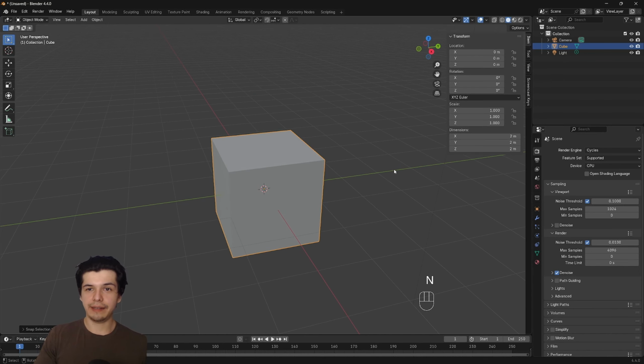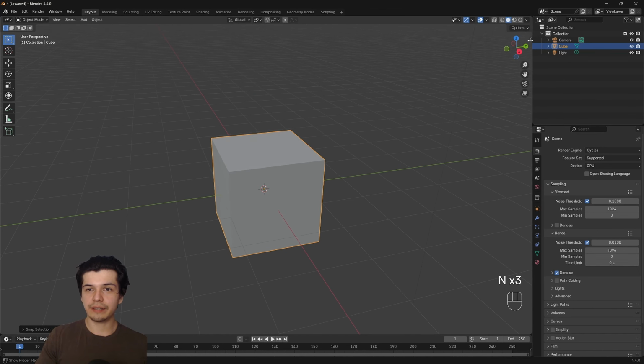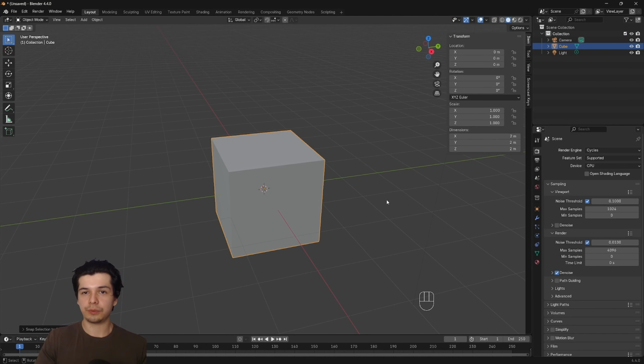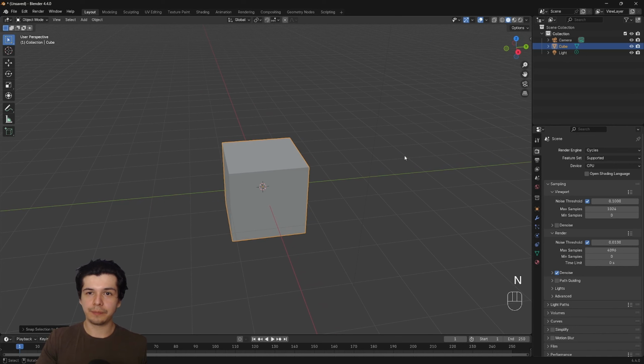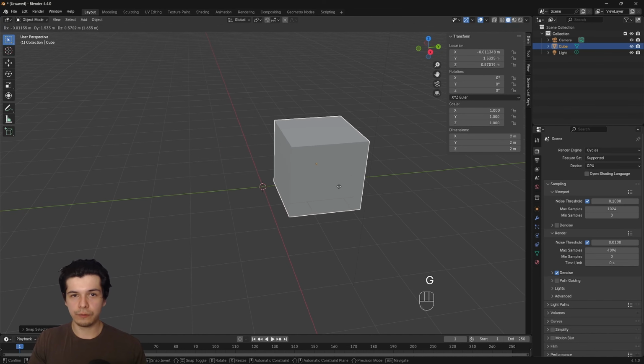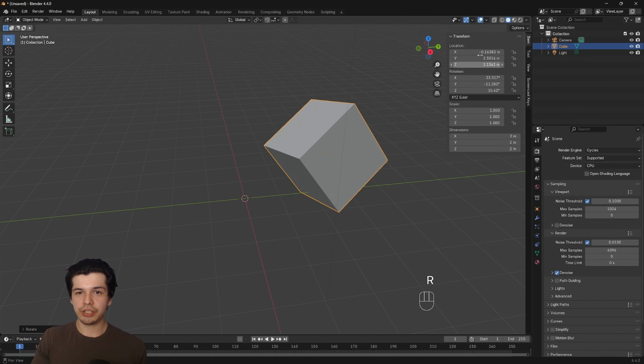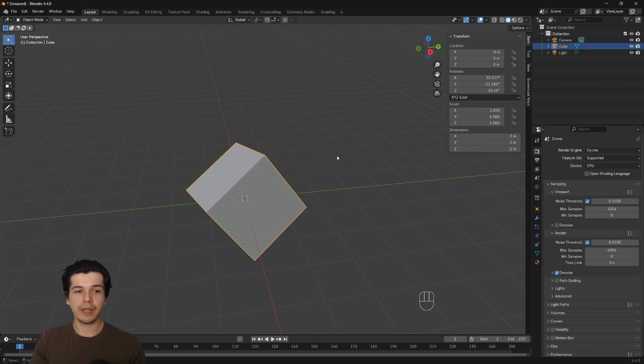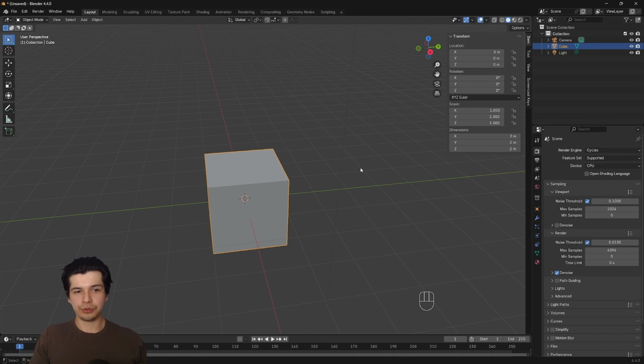Now, if I'm gonna press N, or I'm gonna go right here, there is this arrow on the side. It's very small, but you can see here in the corner, it allows me these extra options. Or in the viewport, if I'm gonna press N, it hides and opens. This is important for us because if we are in object mode and we have moved or rotated the object, you can see it changes the values here. This also allows me to go back from here. I'm gonna left click this one and drag it right away. You have to do it quickly. I'll drag it down. I get all these numbers. I'm gonna press 0 and it brings me back. The same with rotation. 0, I'm back. So this is good to know. If you use object mode for these things, you can get back if you did something accidentally.